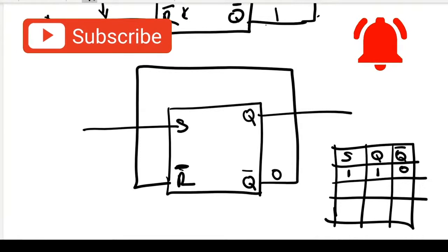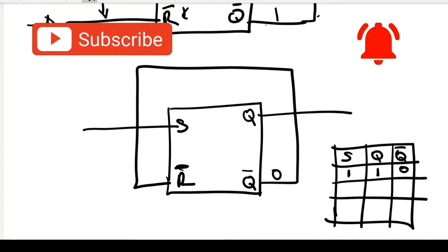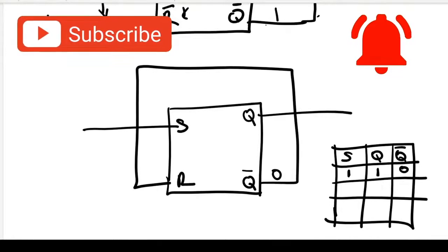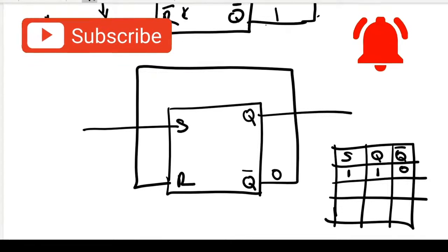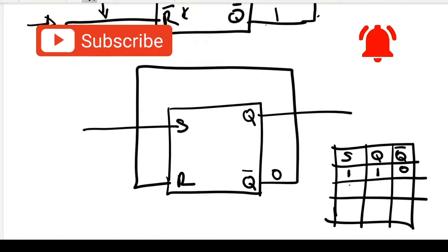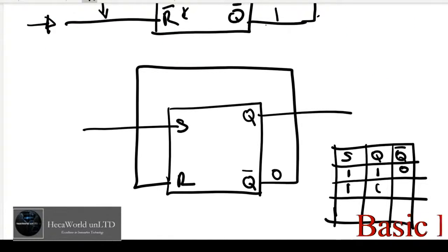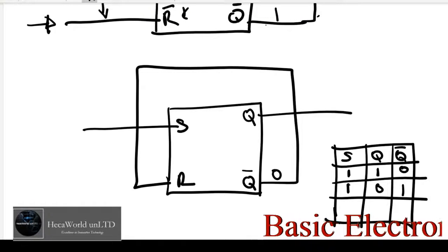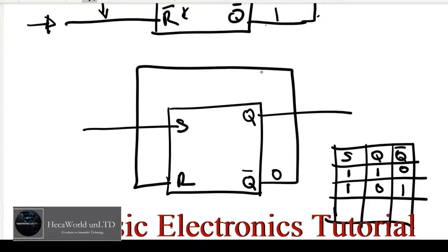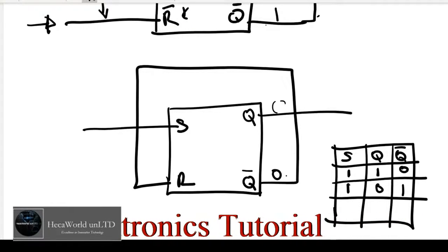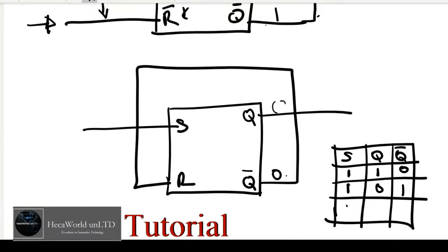So do I want to use this? Let's say I'm using an active high flip-flop. This won't reset my system, but when I clock it again, send another signal, this should now change to 0, and this will be 1. So it's going to function as a toggle. When this becomes 1, it will reset this, and this becomes 0. So this table is going to continue. When I clock it next time, it's going to go 1 and 0. When I clock it again, it's going to go 0 and 1.